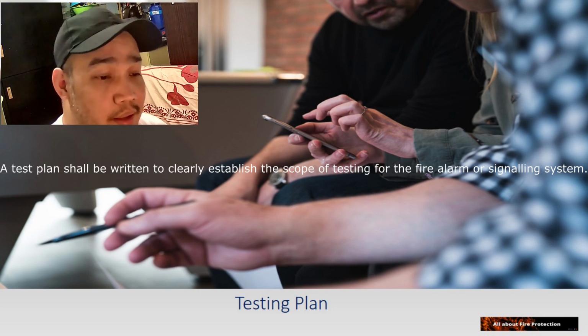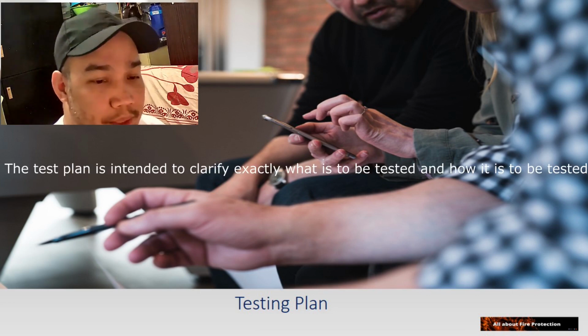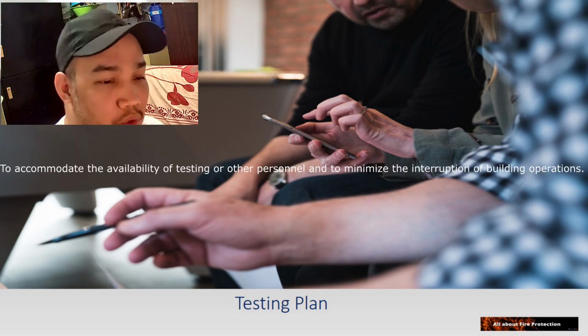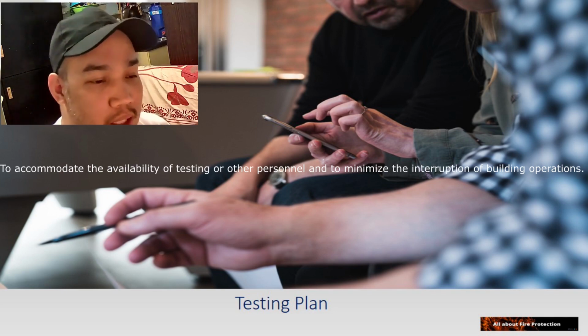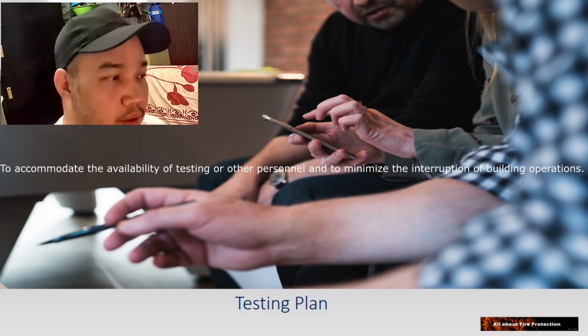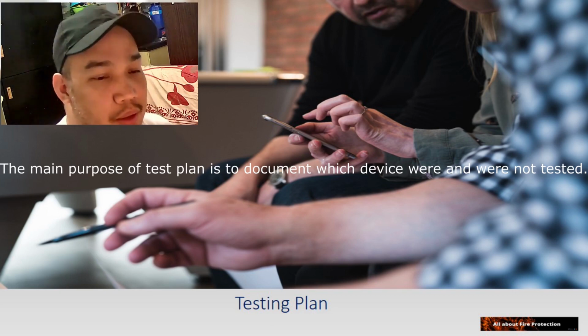And the test plan is intended to clarify exactly what is to be tested and how it is to be tested. Testing of fire alarm and signaling system is often done in segmented fashion to accommodate the availability of testing or other personnel and to minimize the interruption of building operations. The main purpose of the test plan is to document which devices were and were not tested.